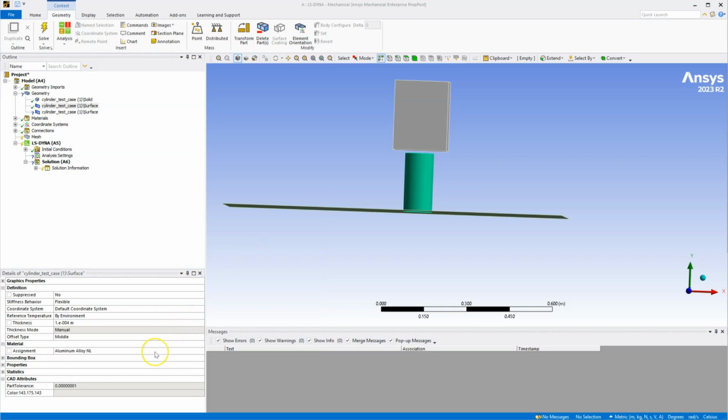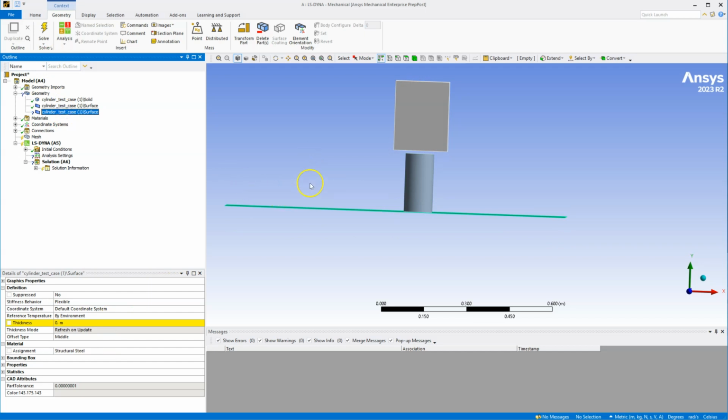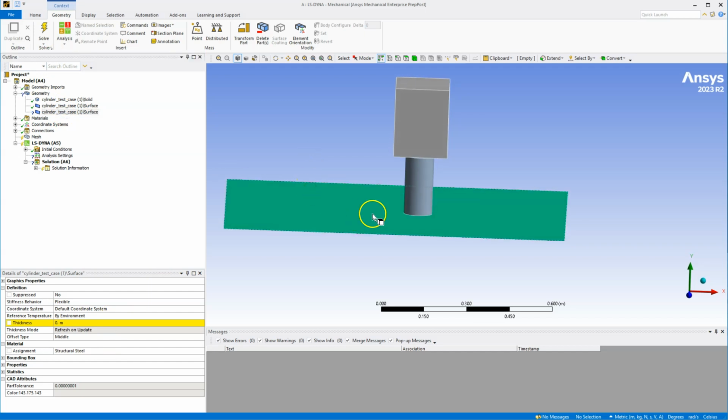But to get more accurate results in an LS-Dyna simulation, I'd need to use a specific material card as outlined in that other video I mentioned. But we're just going to show the capabilities here with this built-in material. Now I'm going to define this floor. I'm going to make that fairly thick to make it rigid. I'm going to make that thickness of 0.1 meter.